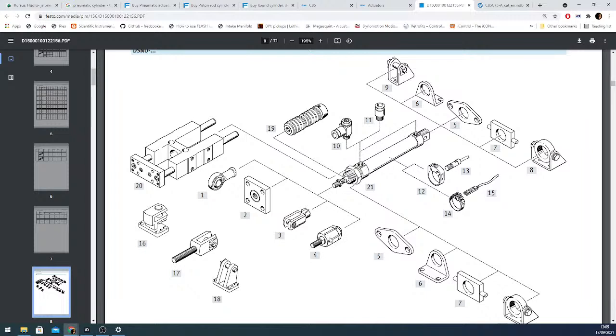But this straight mount is a little bit flexible. It's not just screwing onto the piston rod, it's a little bit flexible. It has kind of a rubbery coupler in here, so it kind of flexes a little bit. It's not completely rigid. And then if you're using those couplers, what do we need another piece somewhere where that coupler mounts to?